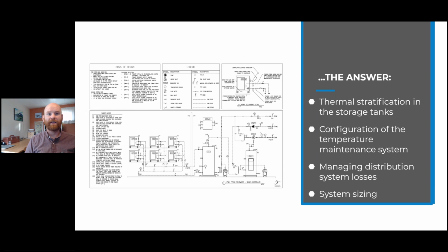And what thermal stratification is essentially a hot water at a usable temperature in the majority of the storage tank at the top, a thin transitional layer of mixed water with a little bit of cool water at the bottom. And so in that design, we have a high level of thermal stratification. If we have a very mixed tank, we don't have that thermal stratification in that tank. And so we want to determine ways where we can prioritize keeping these storage tanks stratified so that the heat pump water heater can operate in a reliable and efficient point of operation.